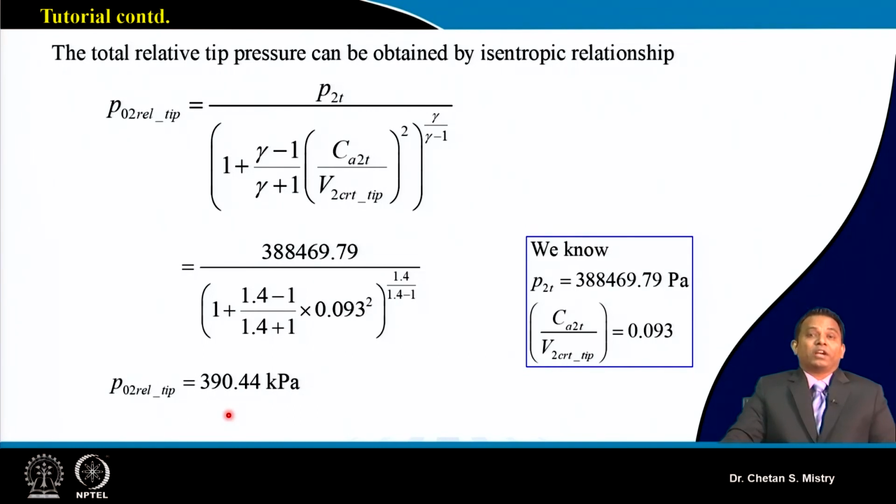By using that data, maybe you can calculate what my total pressure ratio or my overall pressure ratio needs to be, and what my temperature needs to be. If that temperature is off, that indicates something is wrong. So that is how we need to apply what we understand from our basic learning in fundamental courses, and this is the applied part.